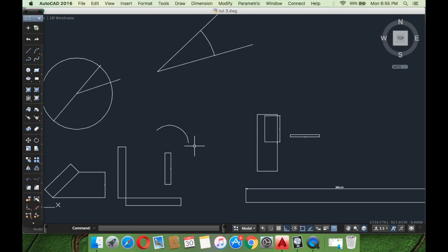Now you can absolutely do that with the help of the command line. You simply type in move. If you type in move, it will automatically give you the command over there. You type it in and then you press enter. You get the cursor, you select the whole object, you right click it, you select the point of reference and give the value, suppose 1,000.